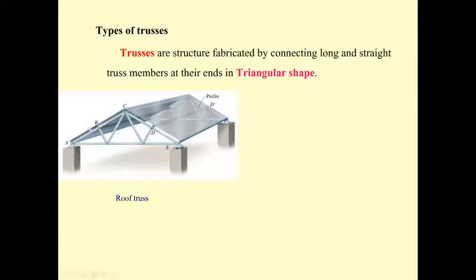So when one truss lays here and another truss lays over here, the worker will lay the purlin and then weld the purlin into the joints of the truss. They're going to lay each purlin, and after they finish laying the purlins and check they're strong enough, then they put the metal sheet, the roof metal sheet, onto the purlin and bolt the metal sheet into the purlin.